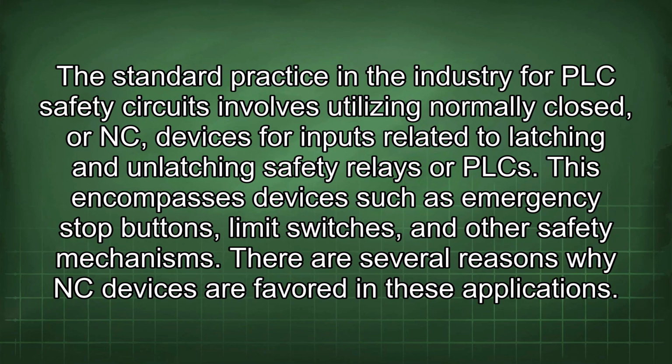The standard practice in the industry for PLC safety circuits involves utilizing normally closed, or NC, devices for inputs related to latching and unlatching safety relays or PLC. This encompasses devices such as emergency stop buttons, limit switches, and other safety mechanisms. There are several reasons why NC devices are favored in these applications.